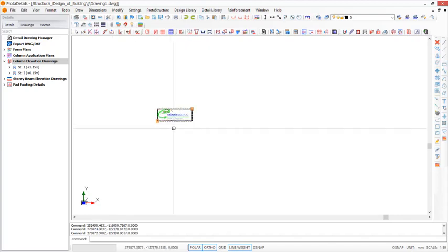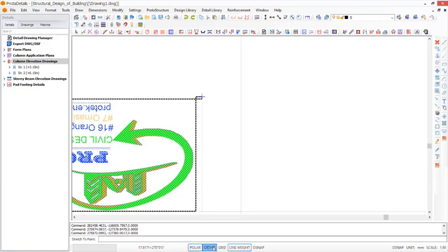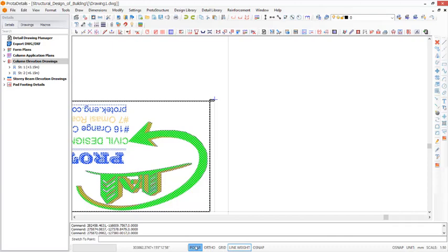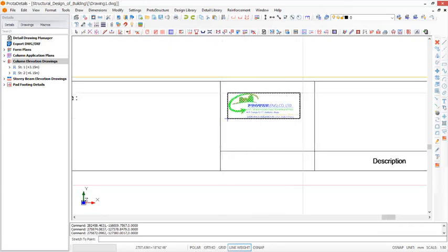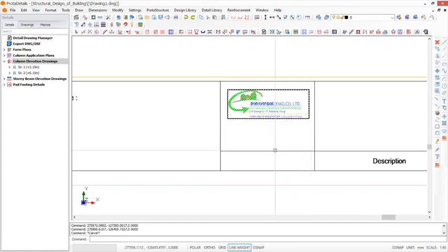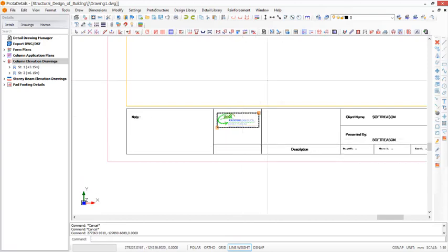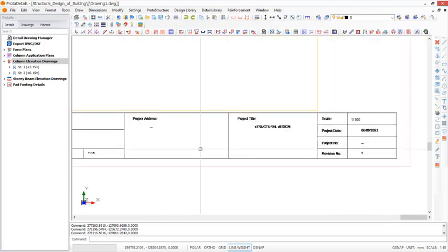You can scale this. Select it, hold this handle, click on it, and then you can drag it up. Mind you, we are on the polar auto right there, so you have to deselect all of these functions to have it expand to your wish. Something of this kind. See now, this is very much arranged. You can move it, just like this. So this is how you make changes to the title block.